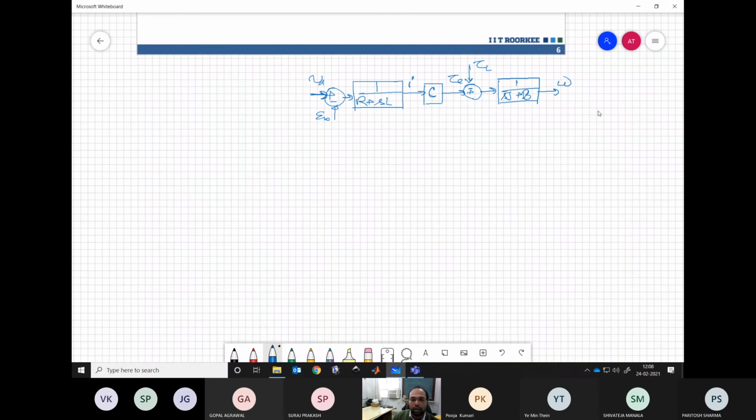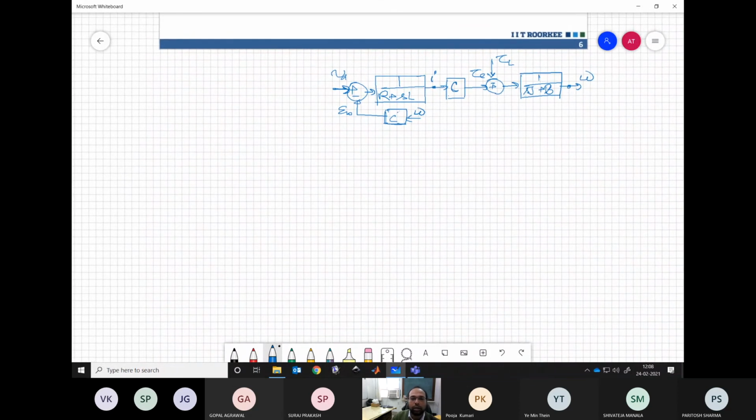Essentially your EB is generated from omega, again a constant times omega. These two constants, the torque constant and the speed or back EMF constant, are the same, and we have these two quantities which can be measured. Now we are trying to have a controller for this system. VA is generated through a power converter. The power converter works on the basis of the reference signal given to it, and gain times that reference input is our output. So our VA is nothing but some K times VA reference. This is the model for the power converter.